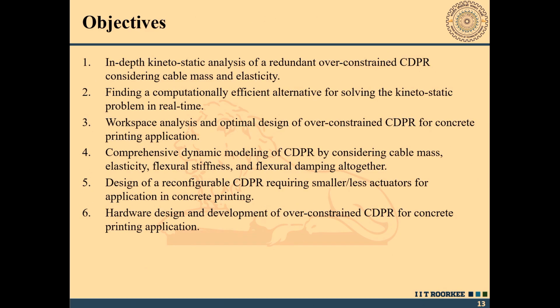So, our objective of the work has been in-depth kineto-static analysis of a redundant over constraint cable driven parallel robot considering cable mass and elasticity, finding a computationally efficient alternative to solving the kineto-static problem in real time, analysis of the workspace and optimal design of over constraint cable driven parallel robot for concrete printing application, and a comprehensive dynamic model also.